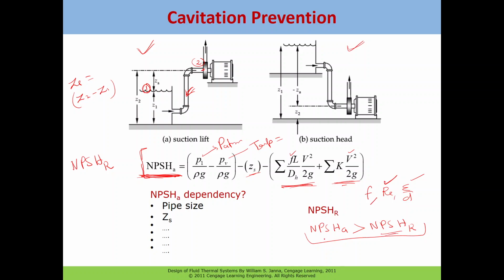that this is the pump requirement. If the system has more than the pump requirement, then it is safe, and if not, then the cavitation will occur. So I hope this is clear now.